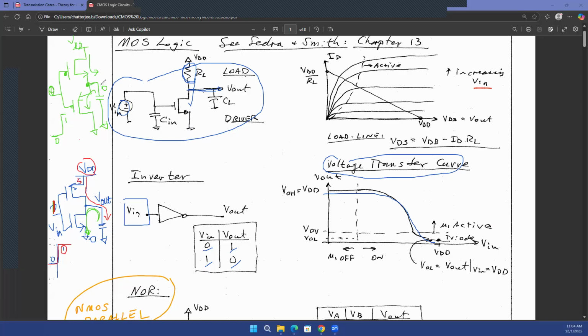The other way people explain it is, the PMOS is a good conductor of the digital 1, whereas the NMOS is a good conductor of the digital 0. If you want to discharge the capacitor, NMOS is your way to go. If you're trying to use a PMOS, you cannot discharge the capacitor to a 0. You'll only discharge it to VTH. On the other hand, if you're charging the capacitor, you have to charge it with a PMOS. If you're charging it with an NMOS, it will only charge up to VDD minus VTH, and after that, the NMOS will go off.